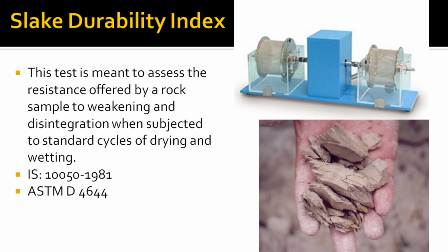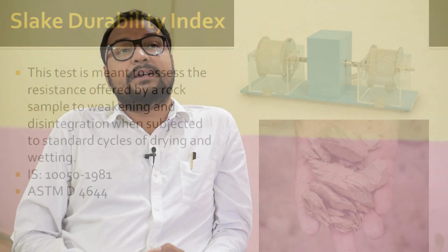Another common test which is routinely conducted is the Slake durability index test. So, what is slaking? Slaking is essentially the dissolution of cementing material in rocks. It's mostly pertinent for sedimentary rocks.